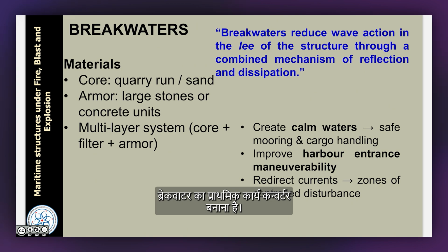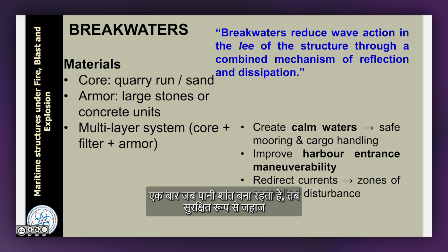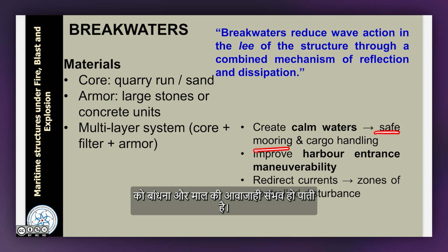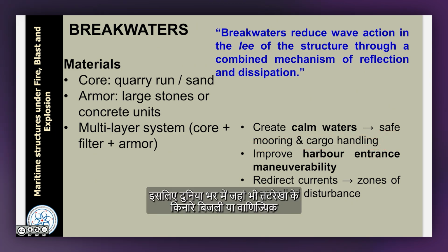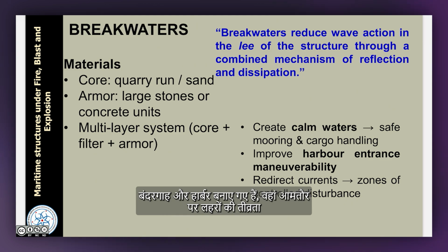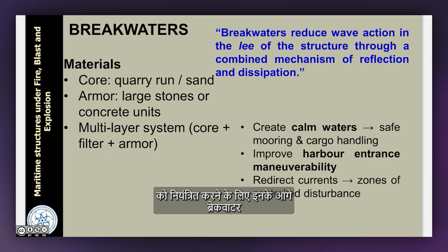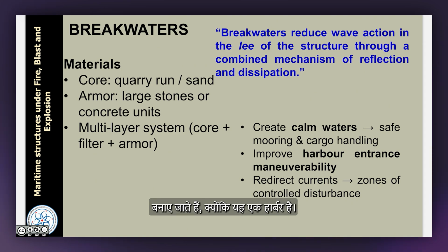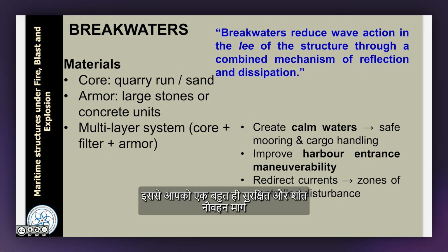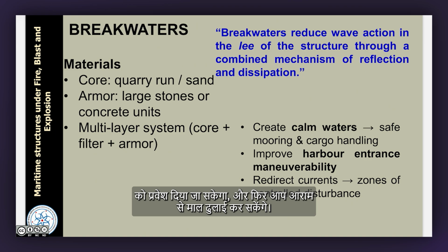The primary function of a breakwater is to create calm waters. Once the water is maintained calm, then one can have safe mooring and cargo handling. Therefore, wherever you have commercial ports and harbors constructed along the coastline in the world, you will generally have breakwaters ahead of these to control the wave amplitude as they reach the harbor. So, that will give you a very safe, calm navigation channel, so that one can admit the vessels inside the harbor segment in the basin, and then you can do cargo handling comfortably.